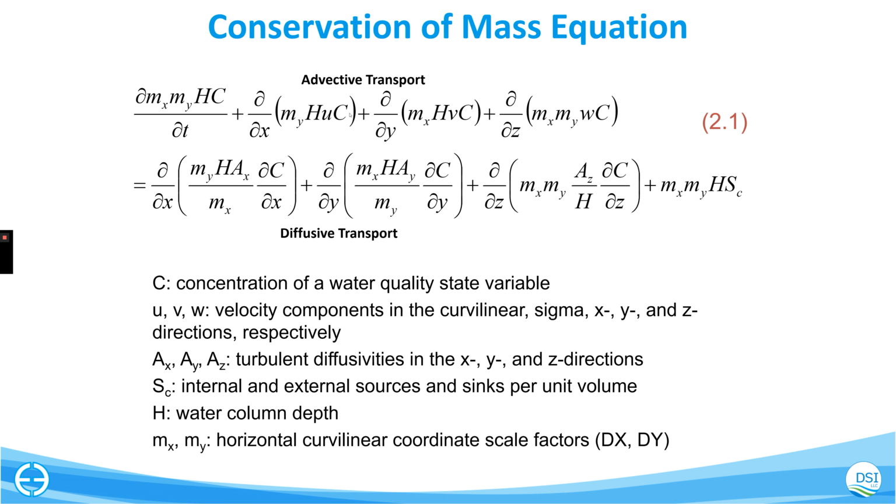As I said, the water quality model is coupled back to the hydrodynamics. It's not a one-way coupling, not just from the hydrodynamics to the water quality, because the water quality, predominantly with respect to the extinction coefficient, affects solar radiation penetration, which affects the hydrodynamics. So it is definitely a two-way coupling, but certainly stronger from the hydrodynamics to the water column.